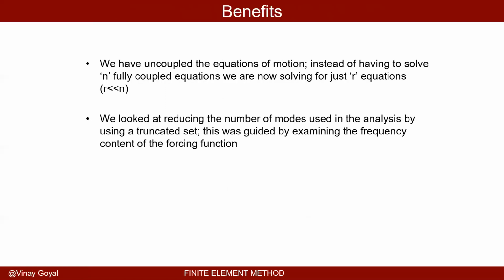But we have uncoupled, I mean, this is the mathematical miracle here, right? We have uncoupled the equations of motion. And instead of having to solve n fully coupled equations, we're now solving a small number of equations. We looked at reducing the number of modes using a truncated set, and we did that by examining the frequency content of the forcing functions and making some smart decisions.